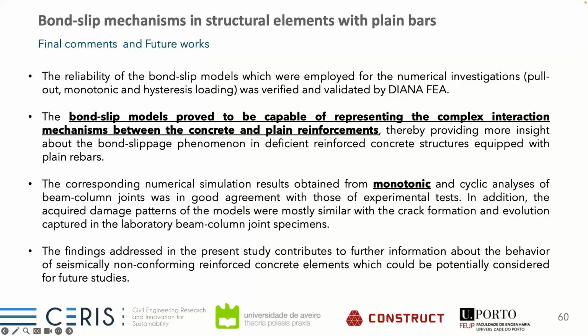They are able to represent these complex interactions, even with plain reinforcement, where this effect is more relevant. And of course, the monotonic analysis, or the pushover analysis, presents a better result. We still have some questions with the cyclic analysis, where we consider that we have a good agreement in terms of results, but we would like to improve. I don't know if adjusting the parameters a little bit could help to understand what could be improved in the experimental results, but also in the end the damage patterns are being captured, which is quite important for us.